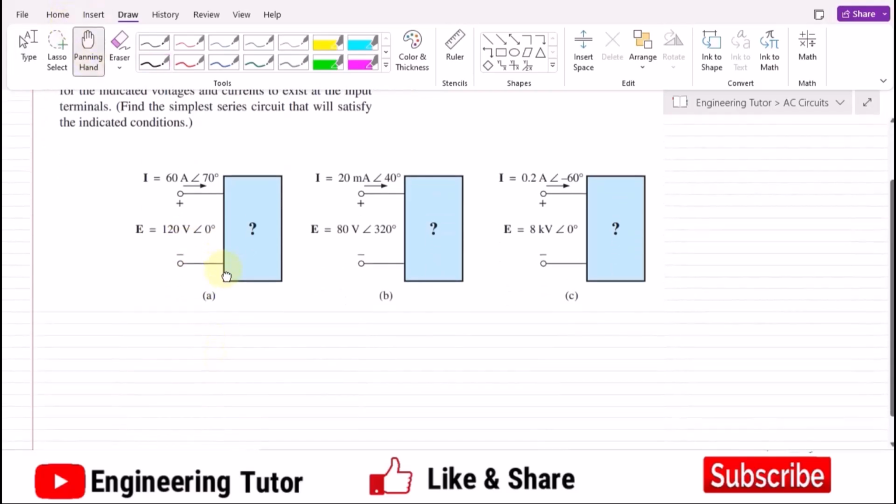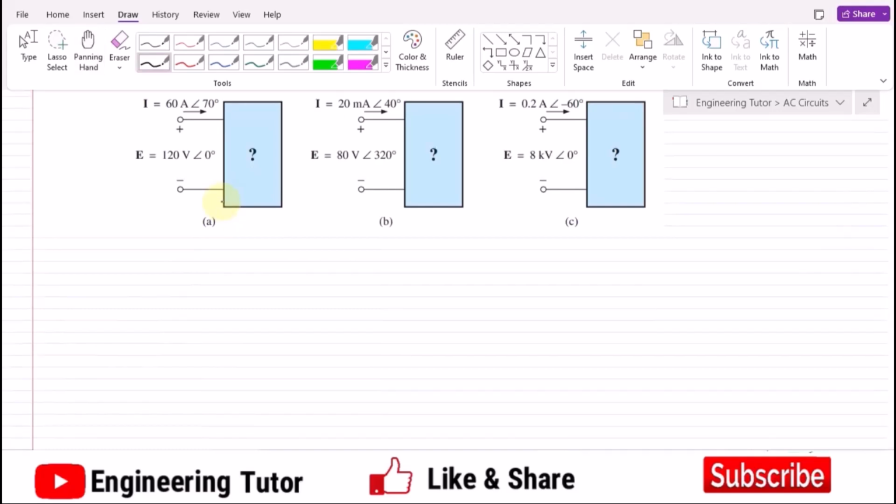Let me start with the first question. In this question we are given the value of current and the value of voltage, and we know that by Ohm's law the impedance is Z equal to V by I. Here V is E, so E divided by I. The value of E is given, that is 120 volts at 0 degrees, and the current is also given, that is 60 amperes at 70 degrees.